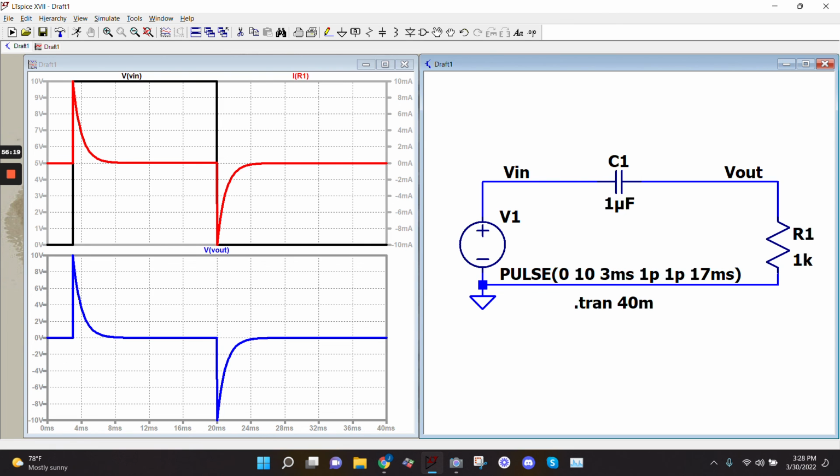I don't know if you guys have ever worked with, trying to think what board it is, some of those FPGAs that we have, there's a power switch and it has an LED, or even any wall regulator that you plug in. If you plug it in and then you unplug it, you're like, whoa, why is the light still on? I just disconnected power. It's because the capacitors are still charged and they're discharging through the resistance of the system. Have you ever seen that?